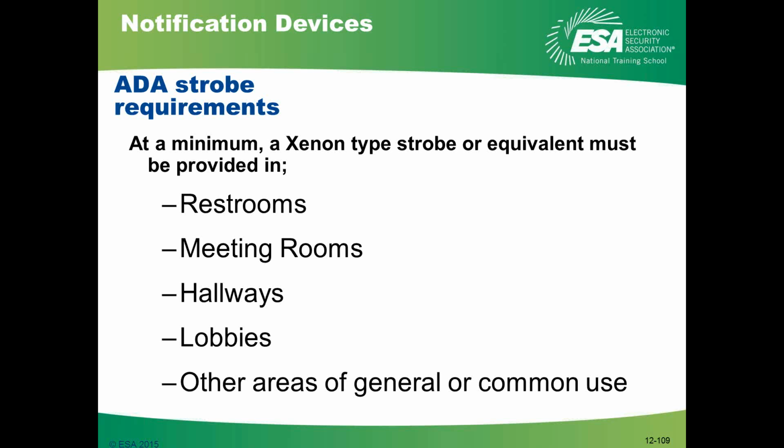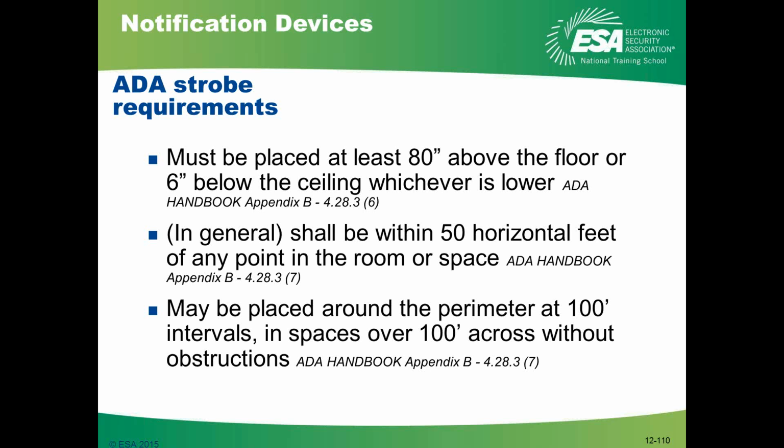ADA only required it in those areas that were accessible to the public. The building code's now requiring it in all restrooms, all meeting rooms, things like this that are general or common use, not just whether they're available or open to the public or not. So it's one of the things to point out here when you're talking ADA.